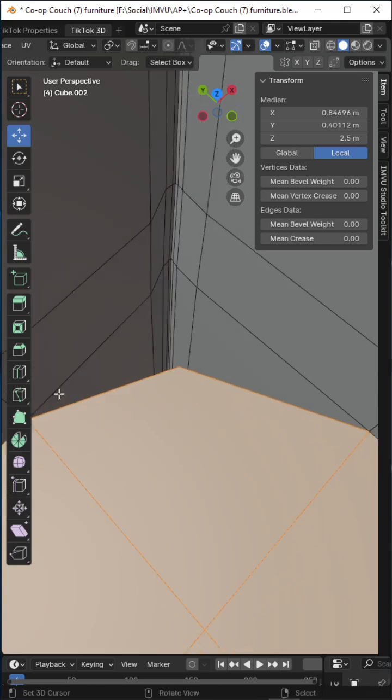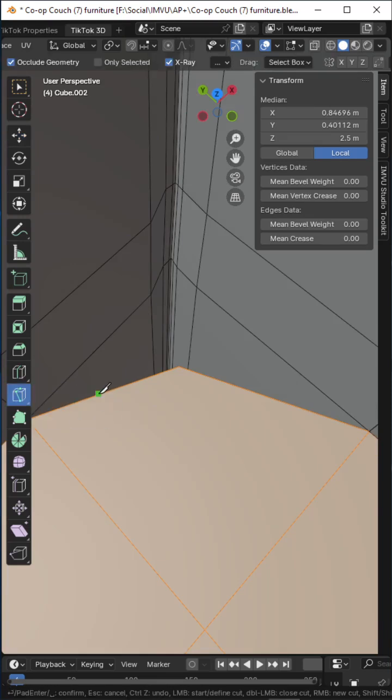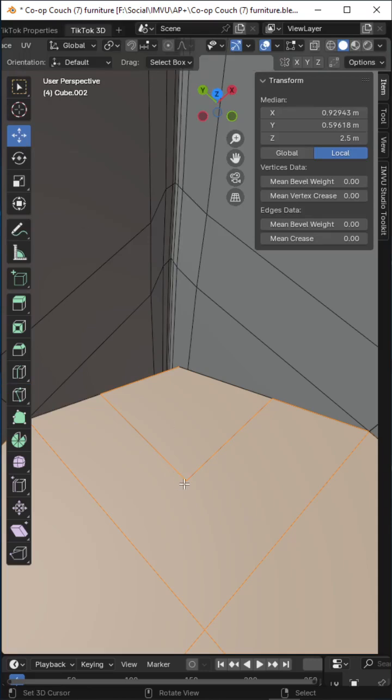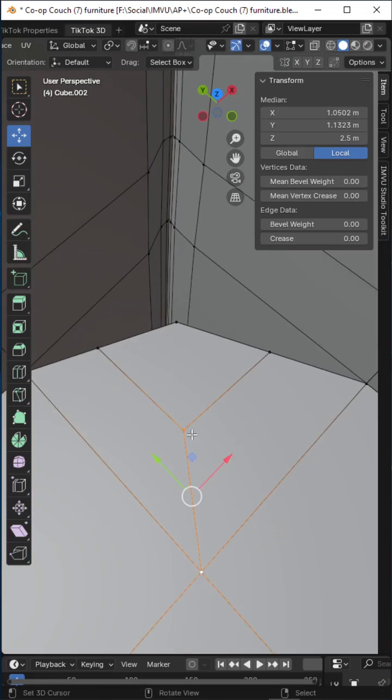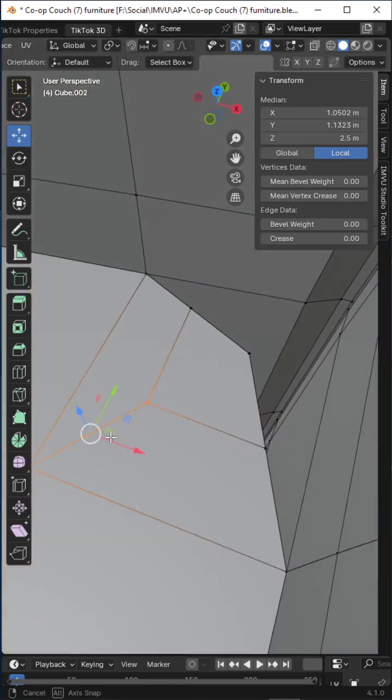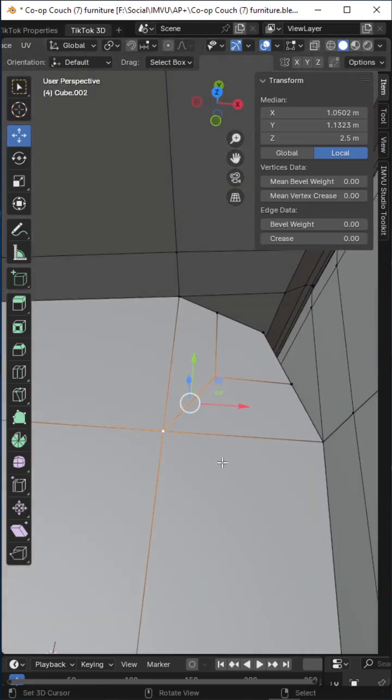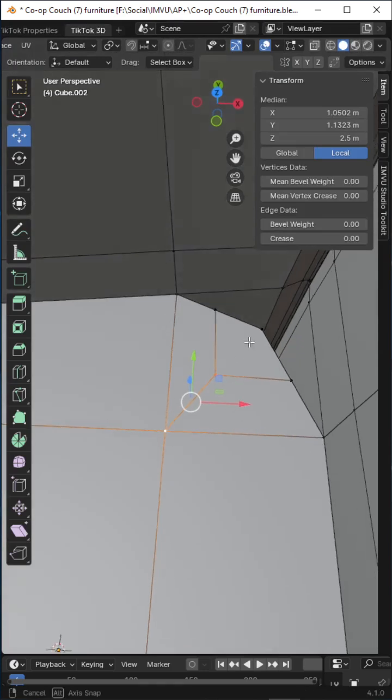So knife tool, yoink, to the edge, return, and then J, vertex, vertex, J, and that splits that or creates an edge between the two vertices. So now we've got a closed quad structure.